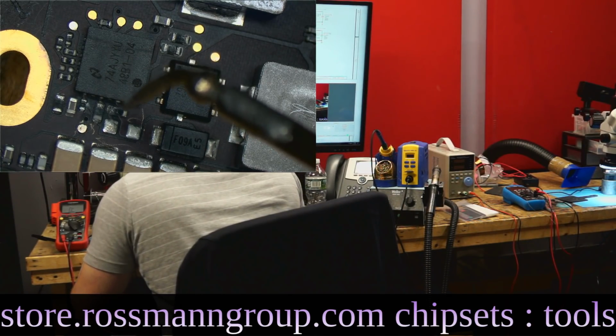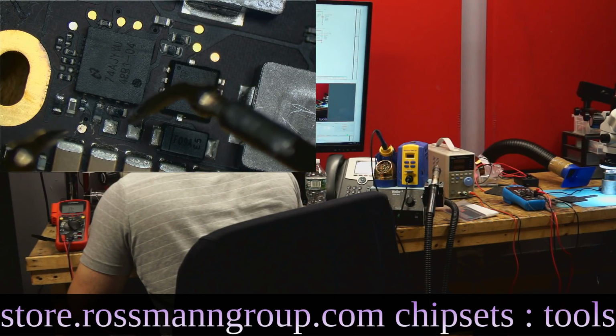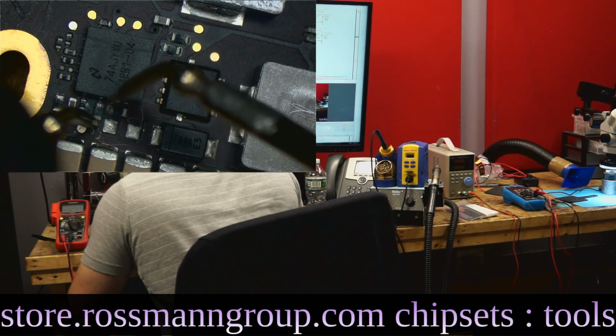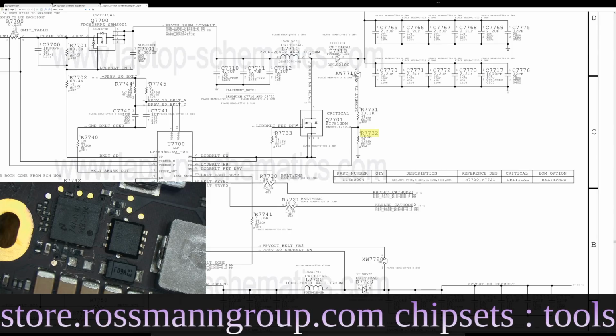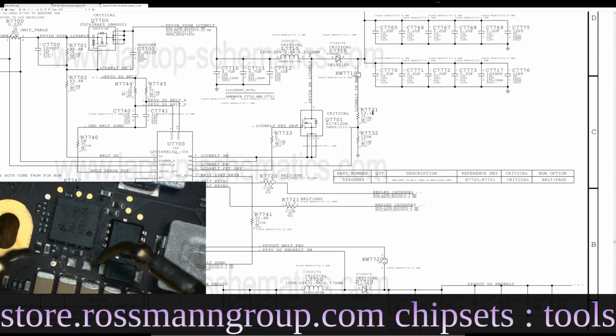So if we look, we have backlight output over here, because these are those caps, and this resistor, and then that resistor going here. So that would most likely be the 13.3 kilo ohm one. And then we have another resistor over here.